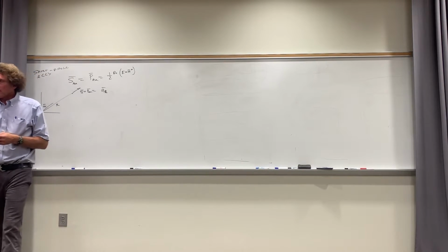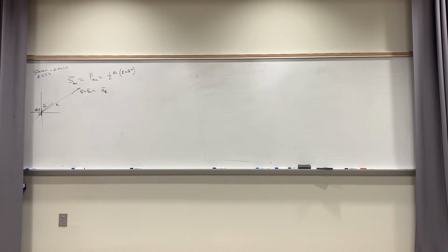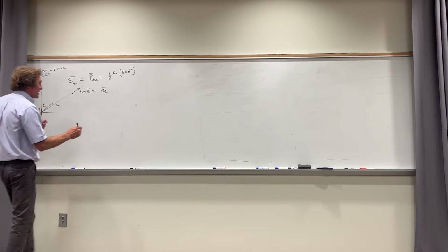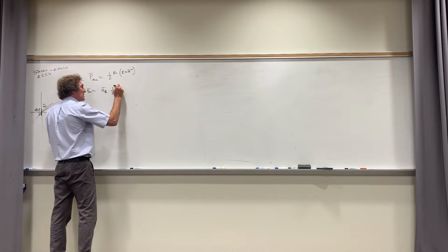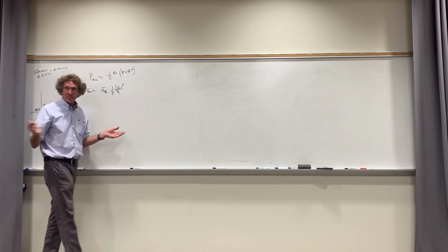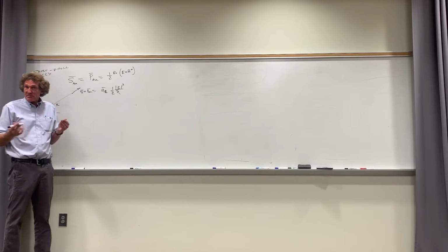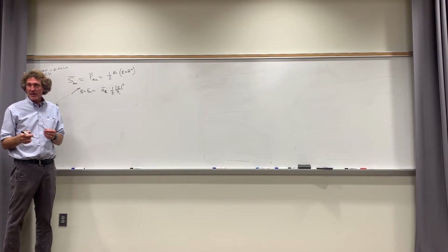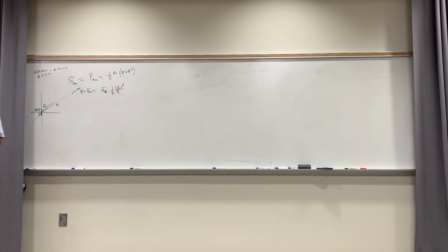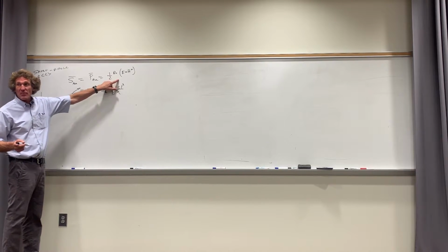Do you remember what the magnitude is for power density for a plane wave in free space? Does anybody? Power density. How many remember it's just given as 1/2 the magnitude of the E field squared over eta? Remember that or not? How many do? E is like voltage, eta is like resistance. Think about it, back in the day when you had AC power, 1/2 the magnitude of V squared, V being the maximum value, divided by the resistance was the power, wasn't it? Same form here. Now you can do this, and he does it in his book just to show you it works.